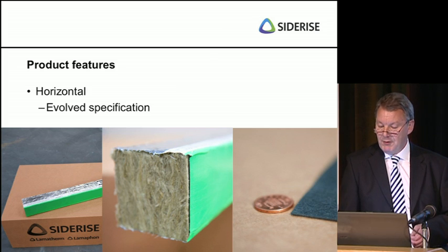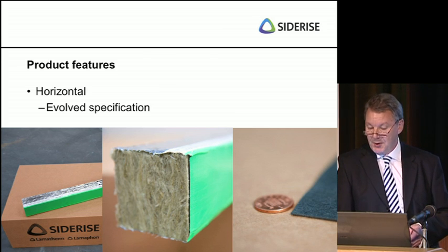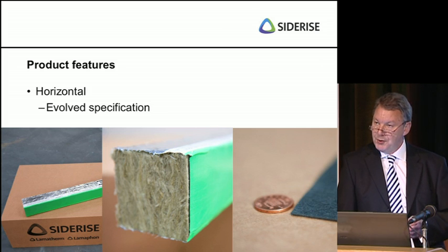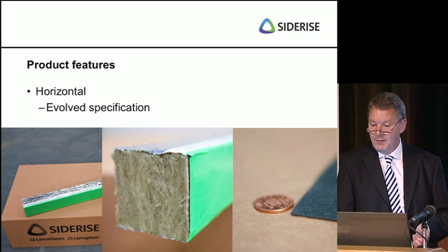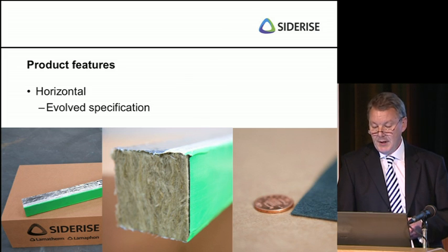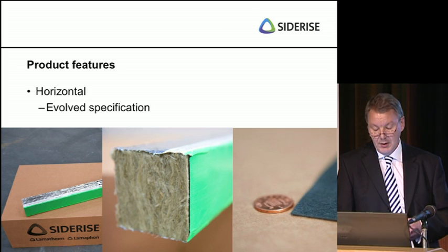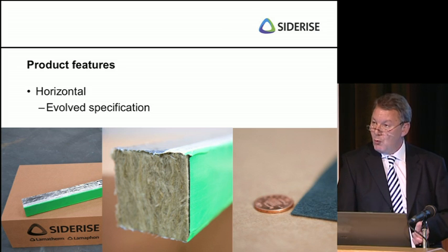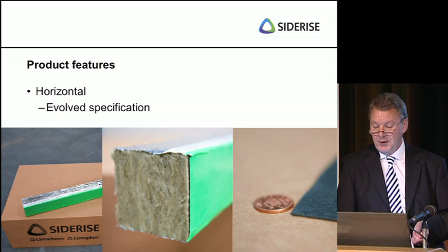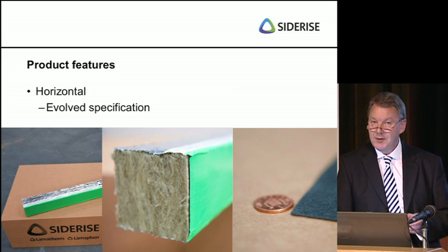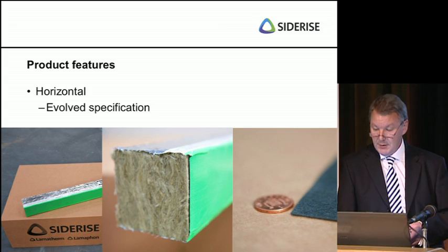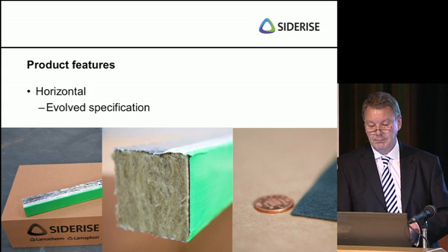In form, they are essentially engineered strips of non-combustible stone wool, faced on top and bottom surfaces with an impervious aluminium foil. Integral high-performance intumescent material is applied to the external leading edge. The system's encapsulated in a weatherproof film which is colour-coded for identification. Green happens to be for horizontal. Simple in concept, because simple is better.